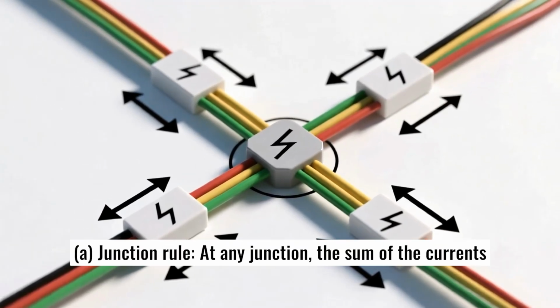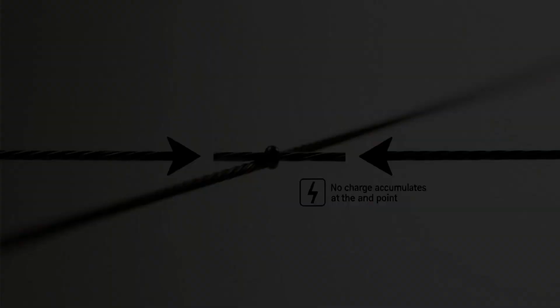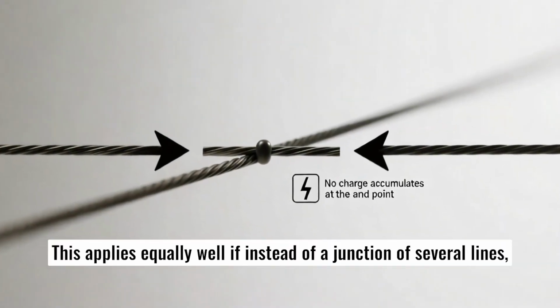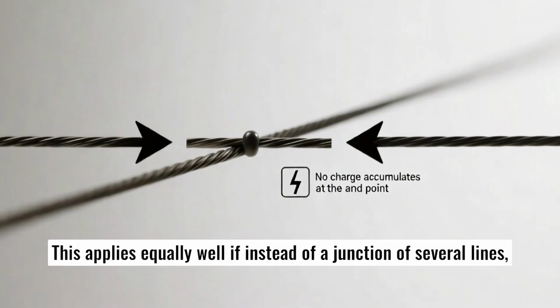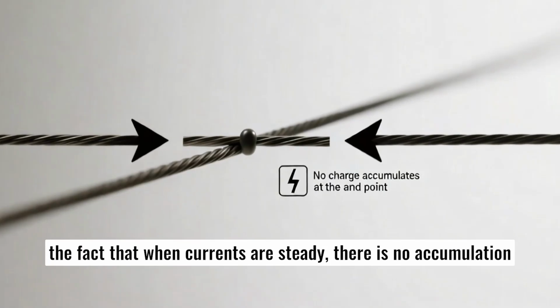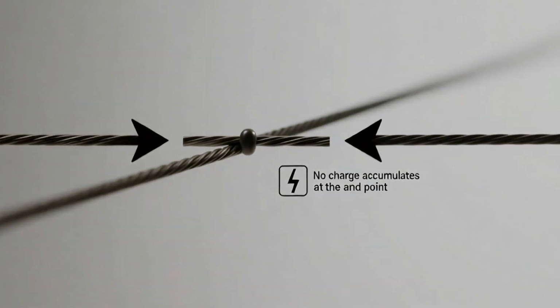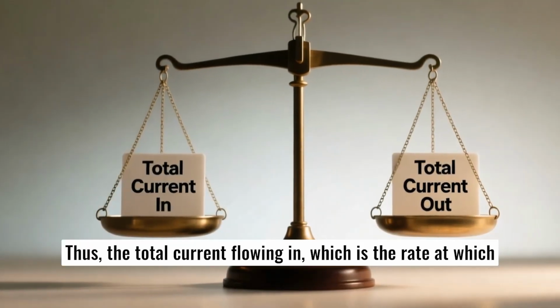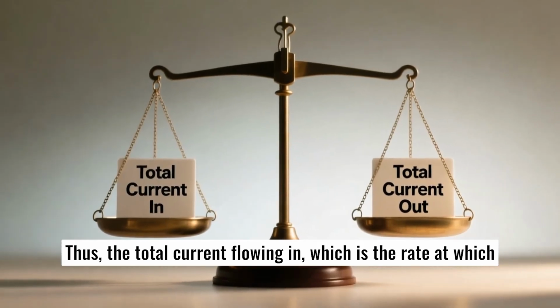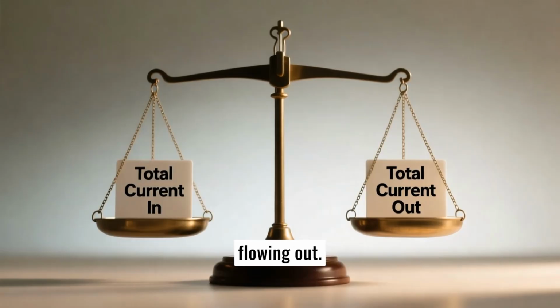A. Junction rule. At any junction, the sum of the currents entering the junction is equal to the sum of currents leaving the junction. This applies equally well if instead of a junction of several lines, we consider a point in a line. The proof of this rule follows from the fact that when currents are steady, there is no accumulation of charges at any junction or at any point in a line. Thus, the total current flowing in, which is the rate at which charge flows into the junction, must equal the total current flowing out.